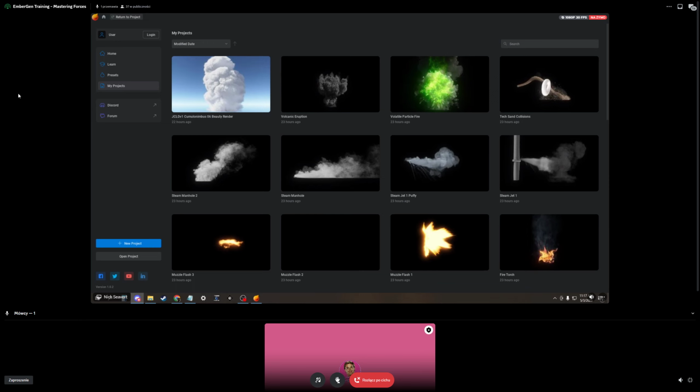If we drag this up, you can also see another force just happened, where whenever I drag this, the emitter is injecting force, and that's controlled by the forces tab with velocity transfer. If we turn that to 0, you'll see that nothing happens anymore. So the smoke is just falling down. There are a number of different force types that are always happening with your simulation. If we go to the vorticity tab and turn this down to 0, we should have some really smooth smoke.